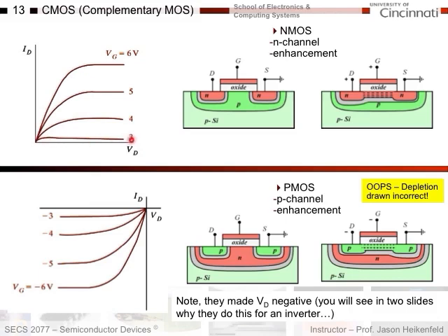And of course, as I increase my drain voltage, I get a linear region at first, but then I run into saturation as the voltage I apply here on the drain, this positive voltage, cancels out this positive voltage, so the channel will pinch off. So in this case of this device here, the channel would kind of pinch off like this, right? So there's my negative charges in there, because the positive voltage here would cancel out the positive voltage here, and you don't get the net voltage drop you need right here to fully invert the channel there.